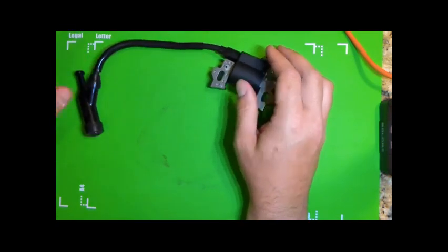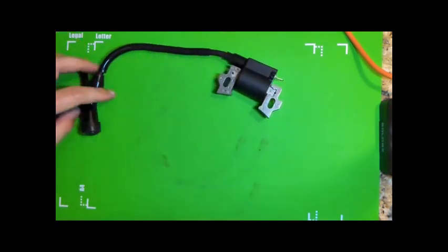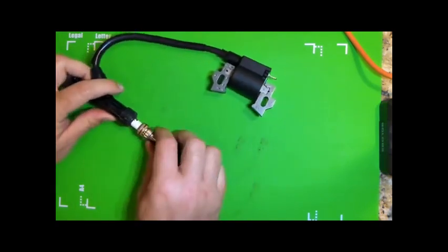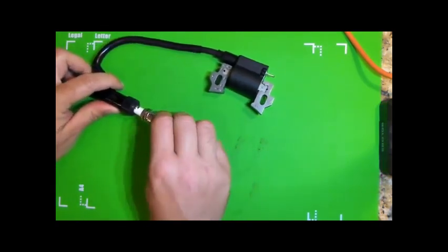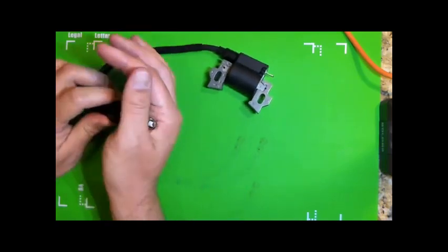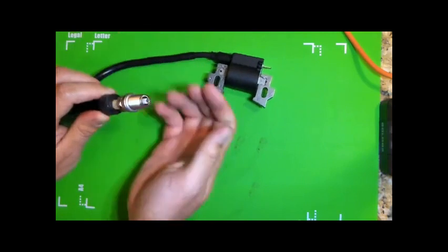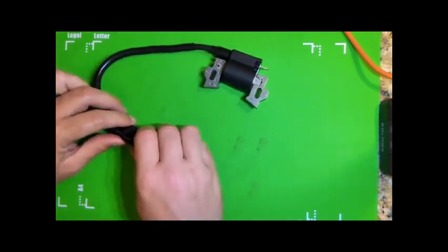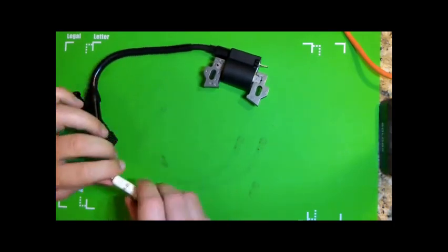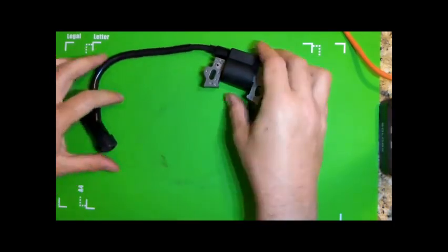Either way, we'll have the same components: the spark plug wire, the spark plug attachment where we insert our spark plug, and then this end of the spark plug that's actually screwed into our engine. This is in the combustion chamber, where we have the gap for the electrical current to jump to actually ignite our air fuel mix. Set this to the side so I don't break that.